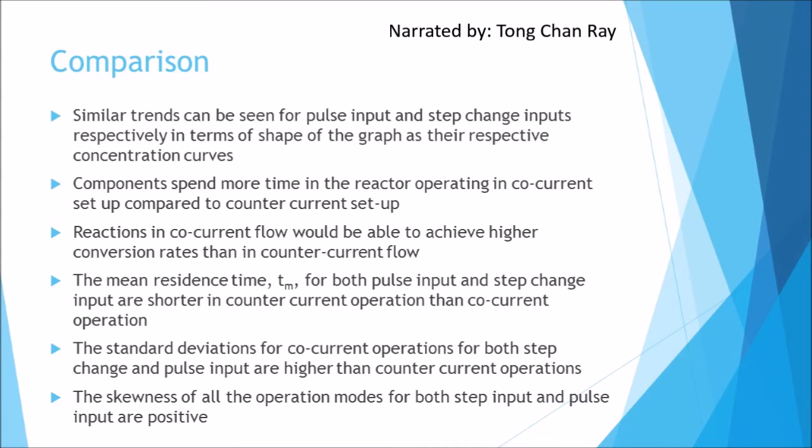Similar trends can be seen for pulse input and step change inputs respectively, regardless of co-current or counter-current flow setup. These trends are similar in terms of shape of the graph as their respective concentration curves. However, it can be seen from the graph that components spend more time in the reactor operating in co-current setup compared to counter-current setup, which also implies that reactants will take a longer time to leave the reactor.